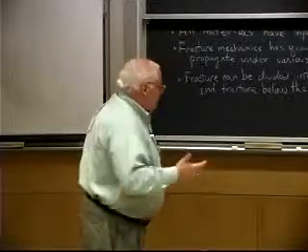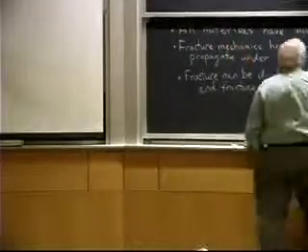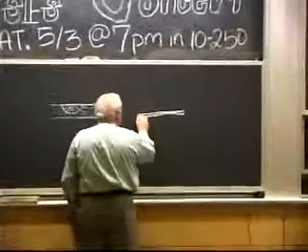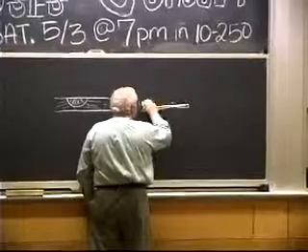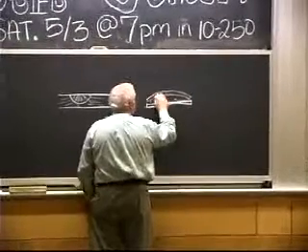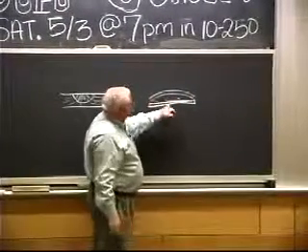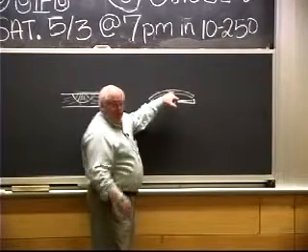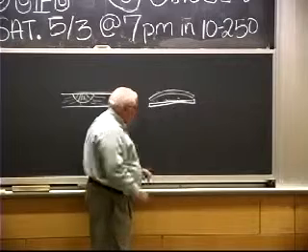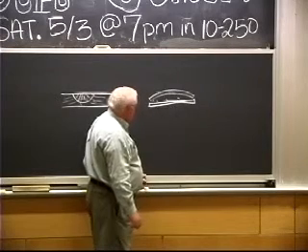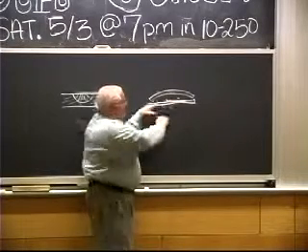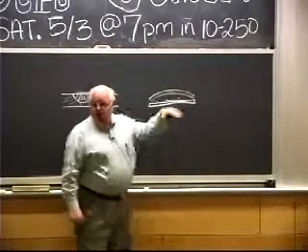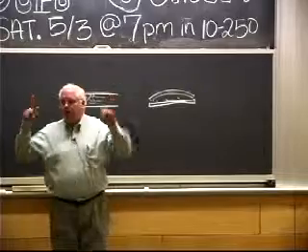And you develop what's called an Almen gauge for this. This is the standard. You take a piece of steel that's flat, and you peen the surface, and after you peen the surface, it'll bow up, because whatever stress you induce in it while you're working it, it'll go in the opposite direction when you're all done. By compressing the surface, you expand the surface, and so when you're all finished beating on it, it will bow up. And you measure the height of that bow, and it tells you how intense your peening is.